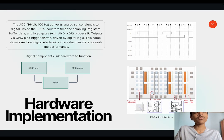So hardware-wise, we have used a 16-bit ADC, which is analog to digital converter, to digitize sensor data at 100 Hertz. Inside the FPGA, counters time it, registers buffer it, and gates process it. So GPIO pins trigger the alarm, all driven by digital circuits for real-time action.